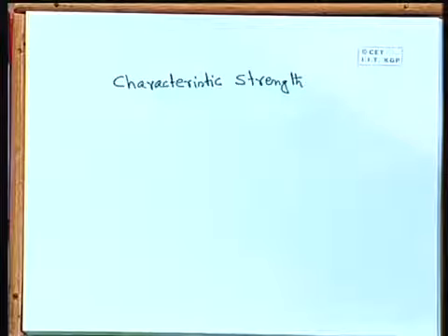If we say M20, why am I telling M20 every time? Because that is the one we generally use. M20 mix 20 we generally use for common design, residence, school building, college building. So any public building, generally we are happy with that M20 grade of concrete. That is a common mix we use. When we use that M20 grade of concrete, mix 20 Newton per square millimeter, we have to achieve that strength, which is called the characteristic strength, and we shall have to find out how I know that we have achieved that strength.